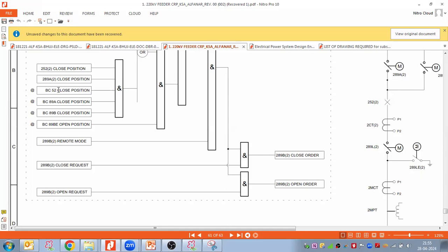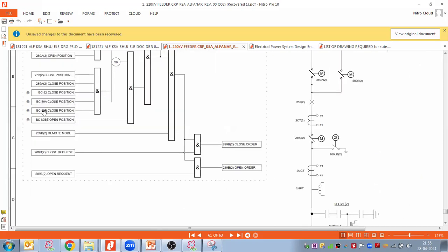Now this bus coupler bay BCU will communicate with my line bay BCU, right? Yes, sir. Since relay 1 BCU is communicating with another bay BCU, this communication is happening as software communication on protocols through the host communications.